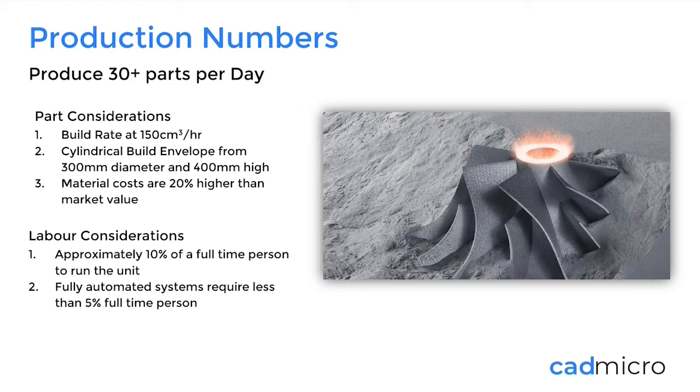Keeping in mind that this is lights off manufacturing, and you can put it on over the weekend or after you leave for work and come back, and you can have liters upon liters of additive manufactured parts out of metal. Another couple industry leading considerations is the build envelope. So you can see I've identified 300 millimeters by 400 millimeters. So you have a foot by 1.3 feet, essentially.